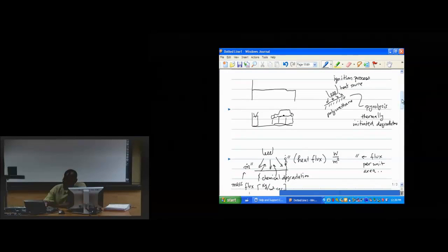I'm going to go back to this diagram, and I'm going to, again, just redraw that down here. But what will happen is that, remember, it's unusual to have just one, what we'll call fuel packet. So we might think about this as the first fuel packet, and anything else in here might be some sort of secondary fuel packet. And there are lots of possible other packets. It could be just the carpeting in the room. There could be wall coverings. There could be drapes. So there are all sorts of different fuel packets within a compartment like this.